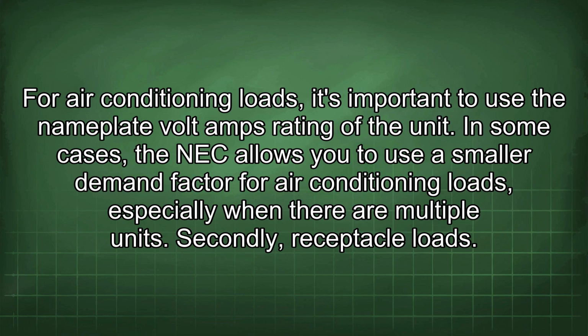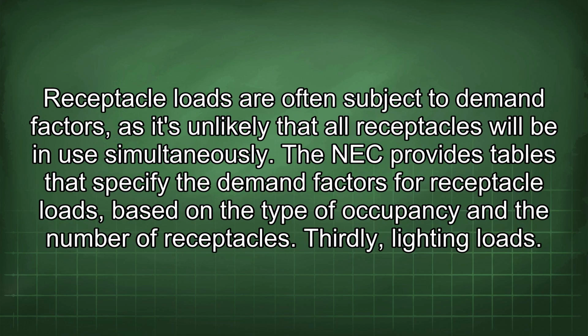In some cases, the NEC allows you to use a smaller demand factor for air conditioning loads, especially when there are multiple units. Secondly, receptacle loads. Receptacle loads are often subject to demand factors, as it's unlikely that all receptacles will be in use simultaneously. The NEC provides tables that specify the demand factors for receptacle loads based on the type of occupancy and the number of receptacles.